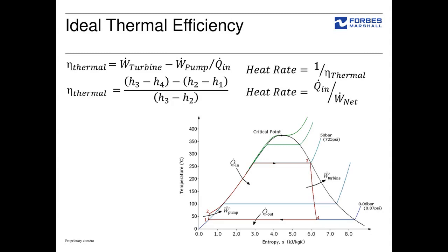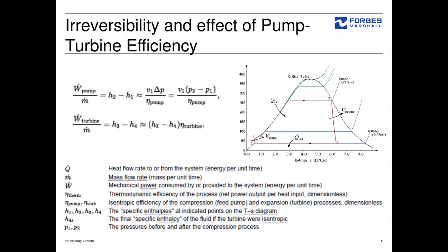It can be easily calculated knowing enthalpy, because water and steam are among the most well-known media. We have steam tables, we have Mollier charts, and that's why by knowing pressures and temperatures, we can plot the entire Rankine cycle for your boiler and turbine, and you can calculate this output quite easily.